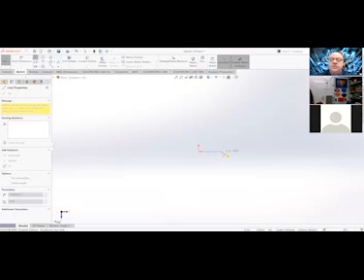So what I'm wanting you to do now is draw straight up, and we're not going to worry about any size whatsoever. You're just going to draw a line of any length and left click. Then I want you to draw a line. Now notice you can get a line that will show you when you're at 45 degrees. In this case, it's reading 135 because it reads counterclockwise. Draw a line at an angle other than 135. So do not do 135, just any angle.